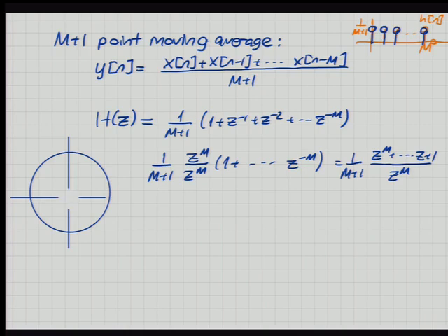Well, sorry. Okay? The reason is, in fact, for any finite impulse response filter, FIR filter, you're going to have an impulse response that looks like this one here, right? Just a finite number of terms in there. And when you take the Z transform, H of Z will look very similar, except that you're not going to have all 1 coefficients. They'll change, right? But nevertheless, to bring it to this form, you'll multiply again with Z to the m and divide by Z to the m. And you'll have this denominator, Z to the m, there for any FIR filter. Okay, so that's a sort of a signature of an FIR filter, that the poles are all at the origin.